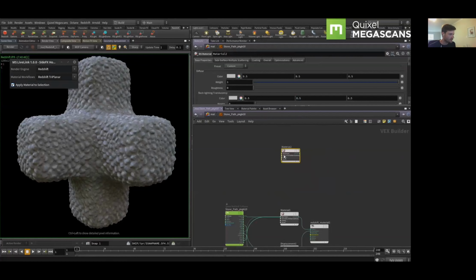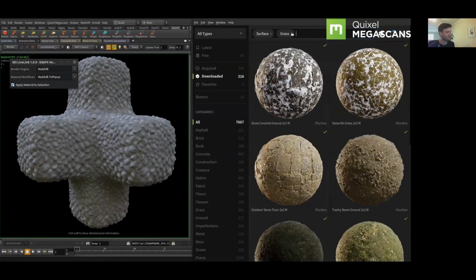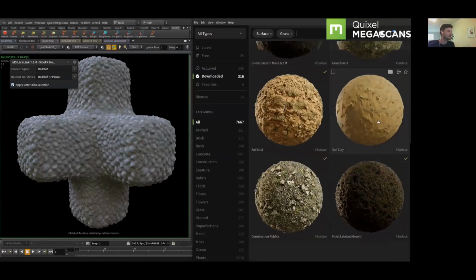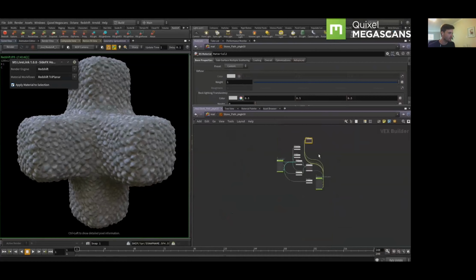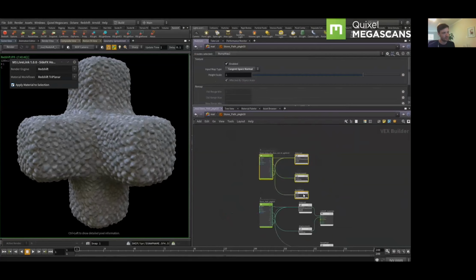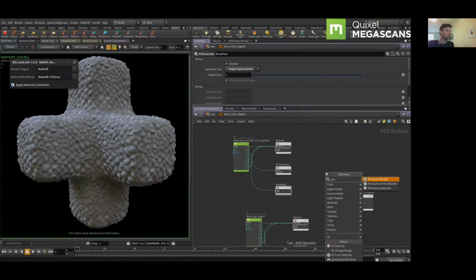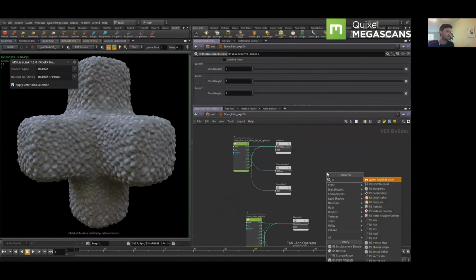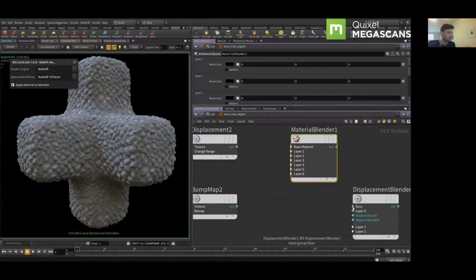So the next thing we'll look at is actually using the Quixel mixer node, to get very nice height blending between different surfaces. So if we bring in, say, this mossy grass material, and we want to layer that on top of the cobblestone material, this is kind of the workflow of that. So because we're using Redshift, there's a slight workflow specific to that, but if you're familiar with how to blend various different materials together in other render engines, the process is quite relatable.